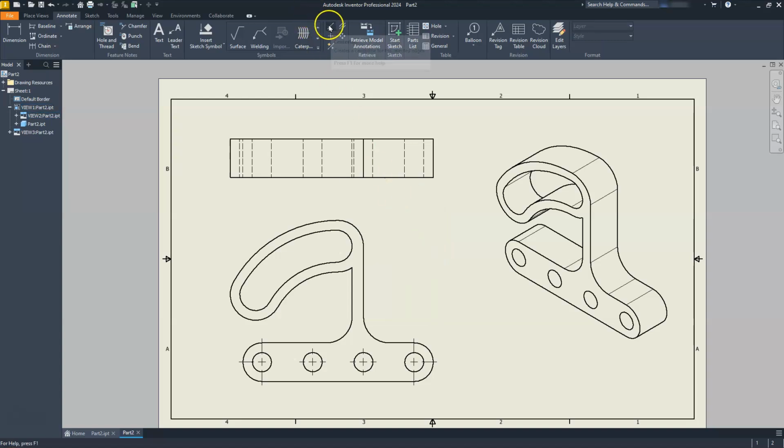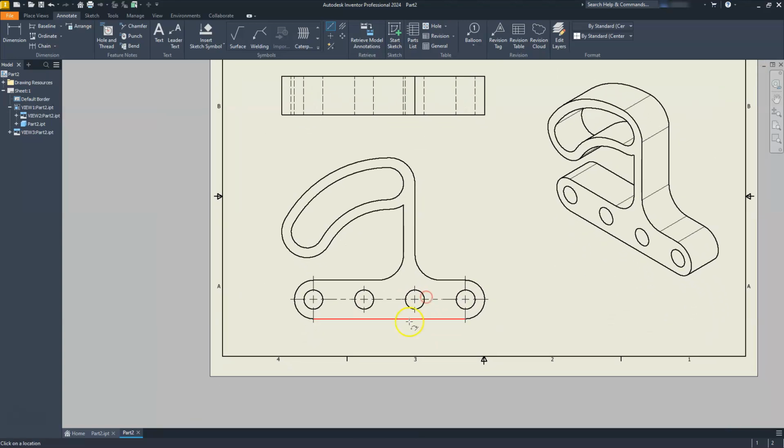And then I'm going to put in these center lines. So I'll go to center line here, click on here to here, and then do a right click and hit create. Go back to that. So I'm selecting here to here, right click create. Select this endpoint to that one, right click and create. All right, so we do have all of our lines there.